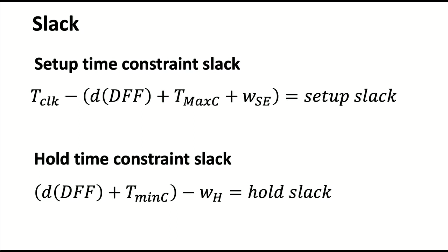Whenever you design these things, you want a certain buffer, shall we say. You don't want to exactly meet the constraint. You want to over-meet it by a certain amount of time, just to cover any issues with estimates that aren't exact, or variations in chips, things like that.